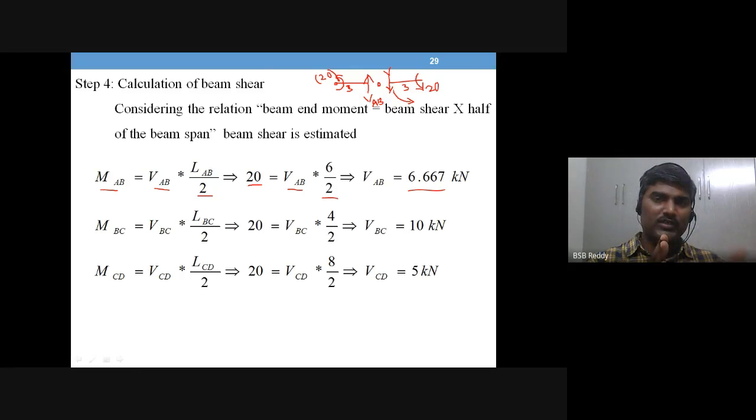to the left of the section and to the right of the section. The shear is always not a single arrow. Representation of shear should have two forces. To cut, to shear, means what? To cut, what do you need? A single force cannot cut the beam. You need to have two arrows. Imagine two knives to slice a particular member.